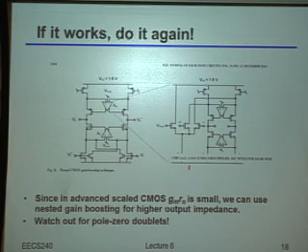Now, it is true that the poles and zeros of this will interact with the poles and zeros of the original circuit. So it is indeed going to be harder to ensure that that's the case. But if you have enough bandwidth out of the technology relative to the speeds you're trying to go at, it is indeed possible to push those out into frequency ranges that are basically beyond where the signal really lies, or where your real bandwidth of interest is.